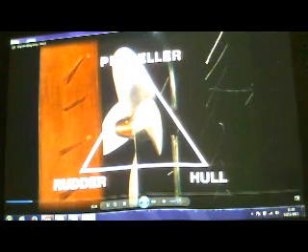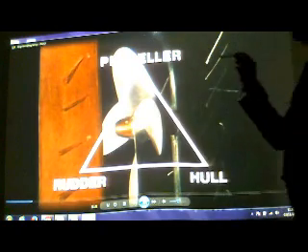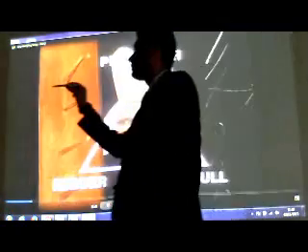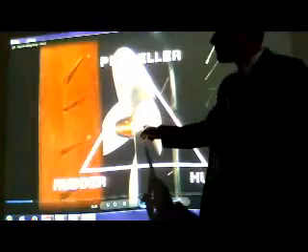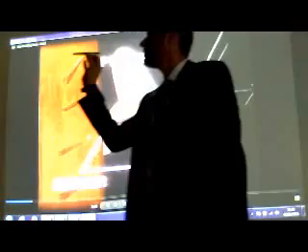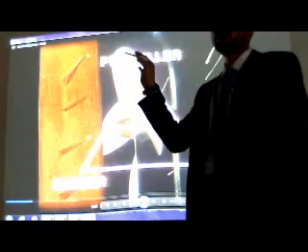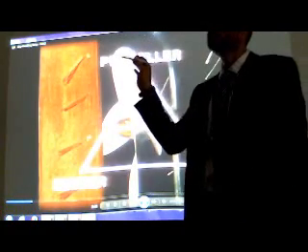Now it talked about transverse forces as well. What is your vessel's propulsion system doing? Because of the longitudinal forces that are applying in the forward and aft direction, your vessel is either moving forward or moving aft. Also because of the inherent design of the hull form and the type of propeller and the rudder and the stern hull form, there are going to be some transverse forces working athwartship to the ship. Which are also important for ship maneuvering. You will look into this, so I'm just highlighting it.